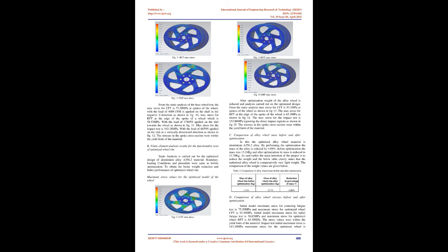V. Weight optimization of wheel rim. Topology optimization is done by removing the material from the rim hub area, where we provide elliptical grooves and pockets to remove unnecessary material. Here mass is taken as the design variable for minimizing the volume. Here the inner side of the spokes and hub area is considered as a design area, while the region's front side styling is taken to be a non-design region. Three appropriate cases are considered to achieve the objective: cornering fatigue test, radial fatigue test, impact test. Base model and optimized CAD model in CATIA after removing material is shown below in Fig.